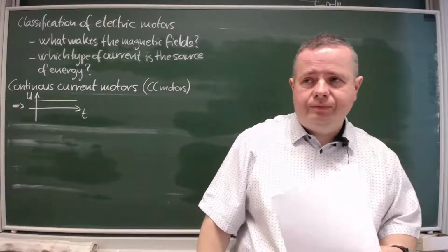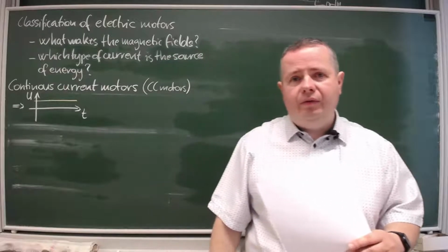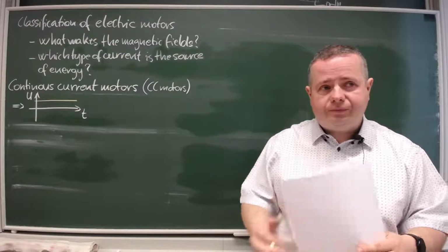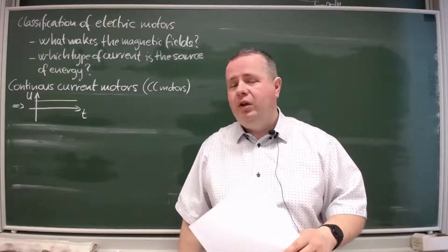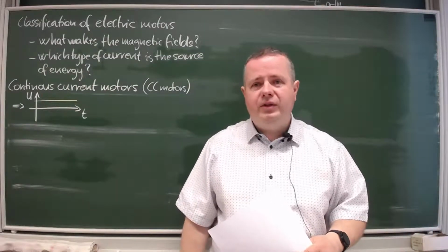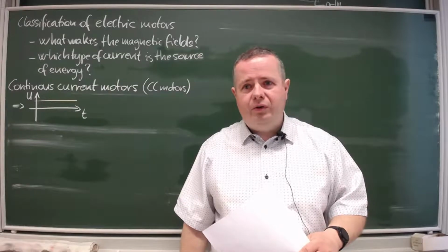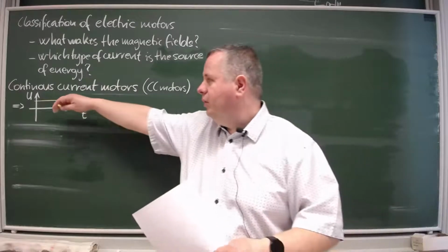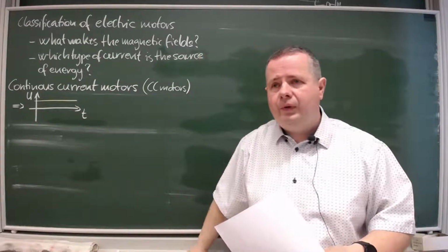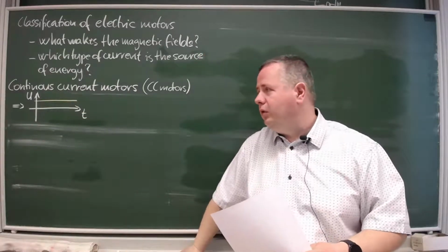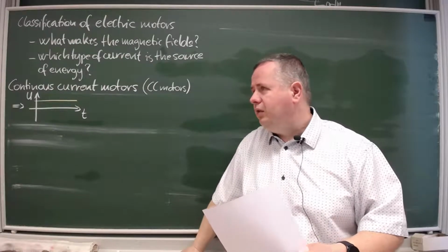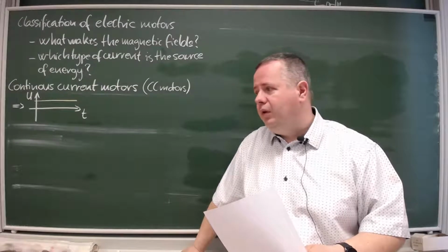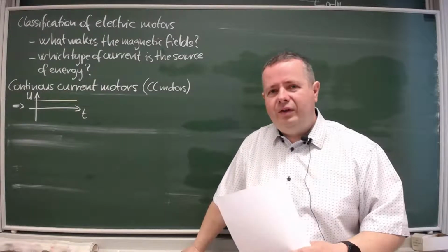Okay? You get a battery of a given tension, or you get a grid, a network for a given tension. In Budapest, for the tramways, we get 600 volts continuous current, which is constant in time. We got 900 volt for the suburban railways, the HEV, and we get alternative current for the normal railway.